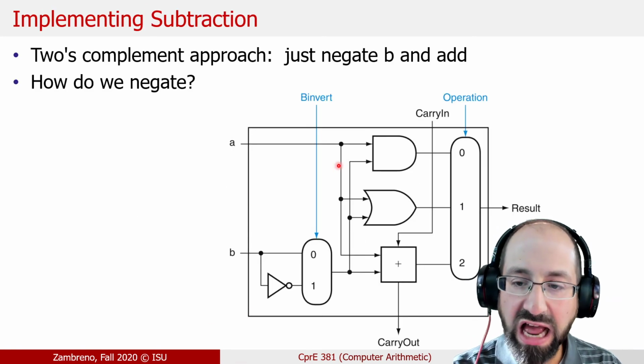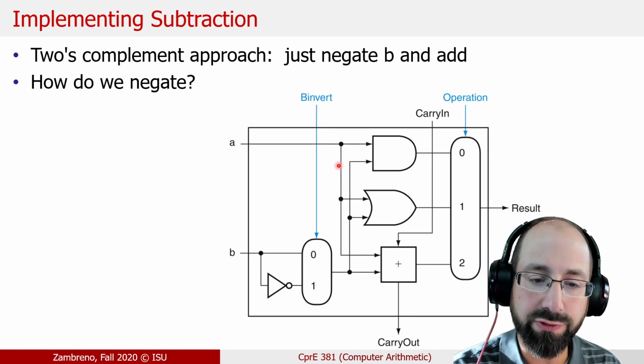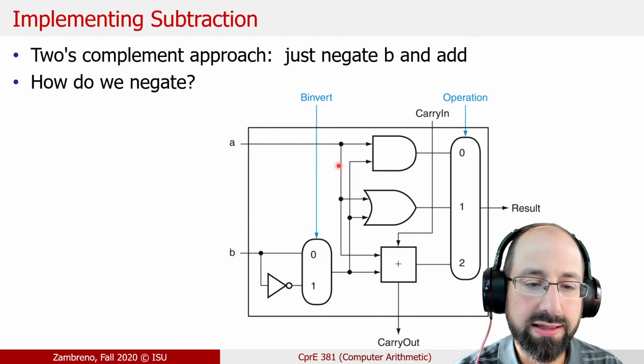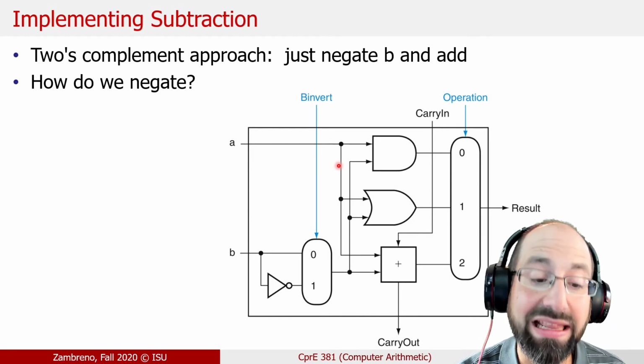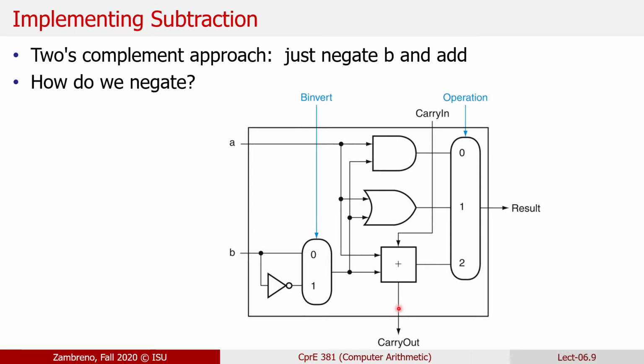And this is the 2's complement approach we did already for lab 2. It's no different. The idea being that to do A minus B, we can do so via negating B and then just adding them together. And we do the 1's complement, which is literally just inverting the value of B. And then we also have to trigger the carry in bit as well. That part of your design for project part A should be identical to what it was for lab number 2. And that's okay. If you didn't get that working for lab number 2, here's your chance to get that working.